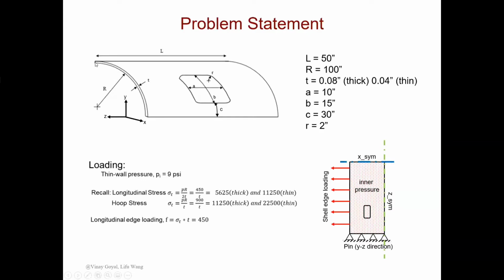This surface is perpendicular to the x-axis, so we should apply the x symmetry to this surface, like this. And since this end surface is perpendicular to the z-axis, we're going to apply the z symmetry on this end.